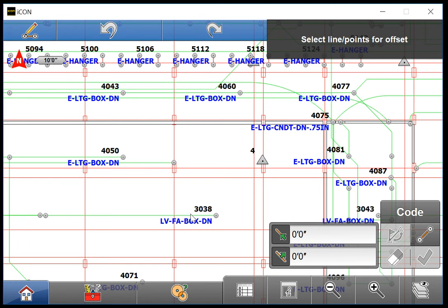After you've measured and marked your offset, you'll want to use the tools that we've covered in this video to create the point at the same offset you measured on the deck, so that you have 2 points to use for your Setup Anywhere function. I will now use the simulator to show you an example of this.